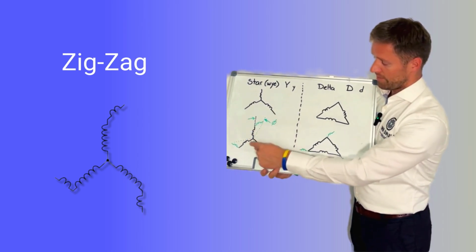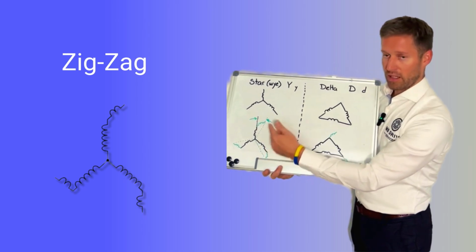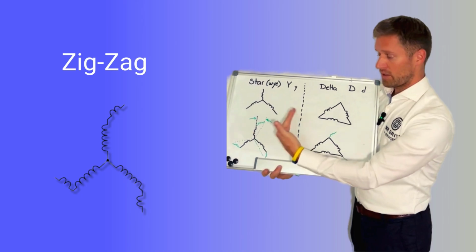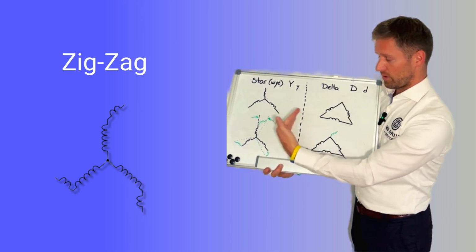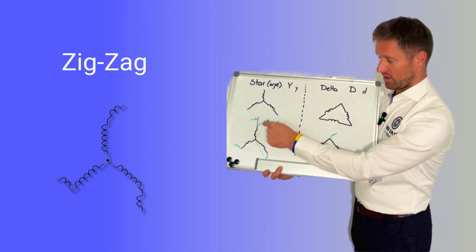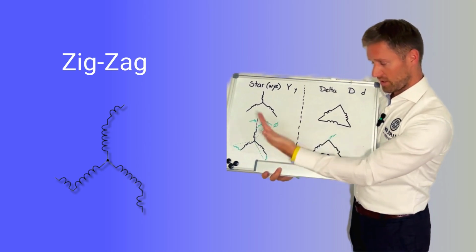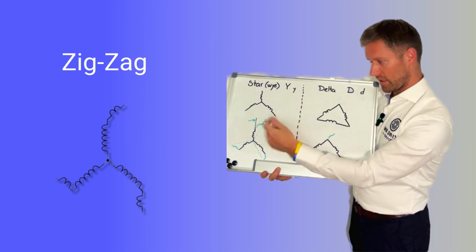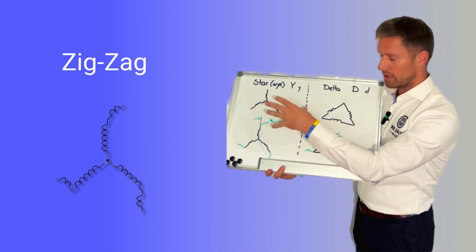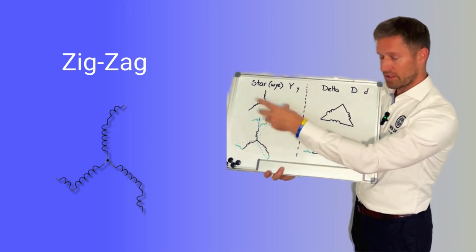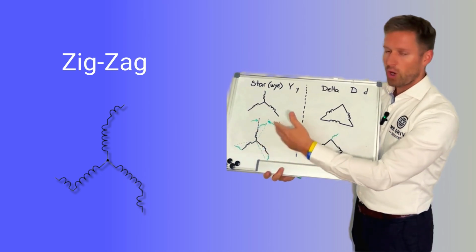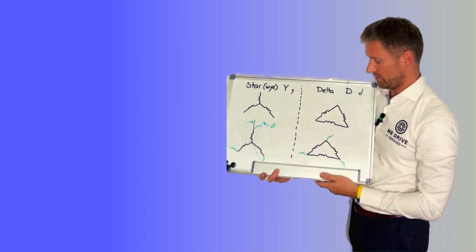So this would be the angle of this zigzag with respect to the original star connection. And in this way we can produce an angle, a phase shift, that is smaller than 30 degrees. It just depends on the number of turns. If we are only adding few turns, then we are just creating a little angle. If we put more turns, we make the angle bigger. So we are not bound to the 30-degree system and its multiple, but we can create almost arbitrary phase shift.